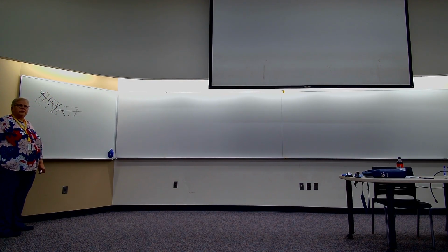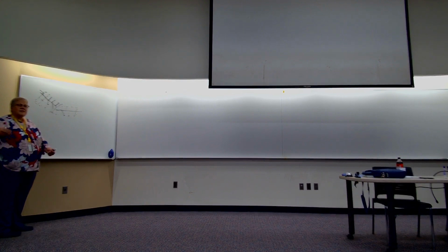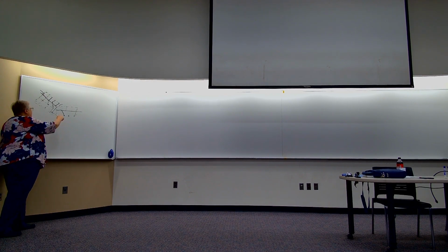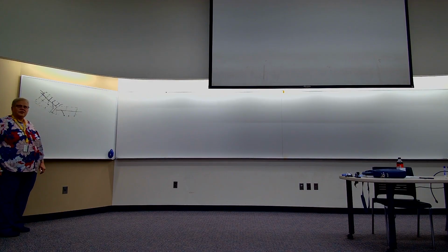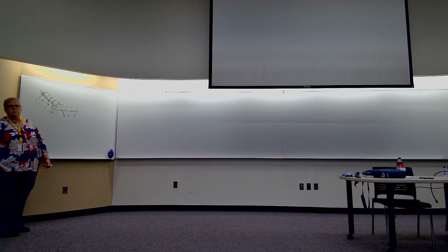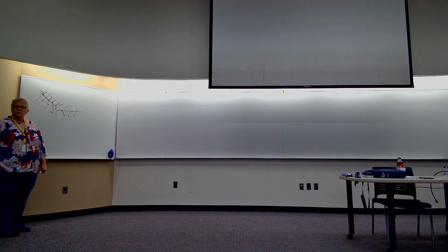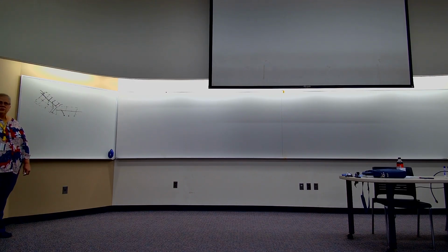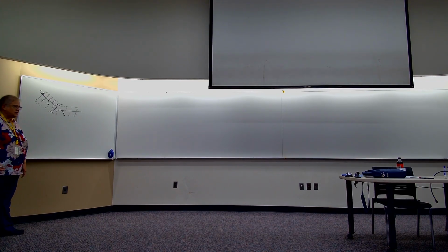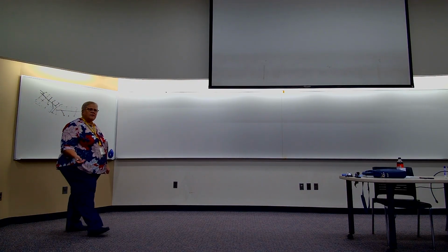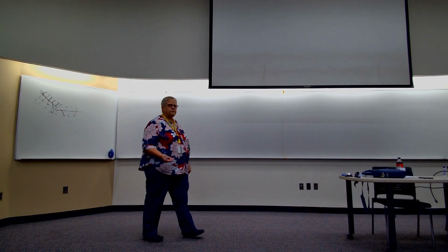So I have this dislocation that's moving on that plane. It reaches a boundary. Now the stress has to go up in order to be high enough to cause that dislocation event. Stress has to go up in order for it to have deformation. That means it's stronger. So these grain boundaries are dislocation obstacles. And if we can add to the number of grain boundaries, we could make a metal stronger, just like adding point defects and adding line defects.